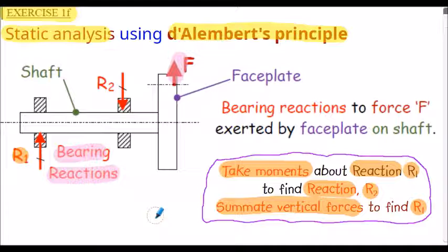So although this is a dynamic situation, the faceplate is actually rotating continuously, we can analyse it as a static situation using D'Alembert's principle and the centrifugal force acting on the faceplate. That is the force that will generate the reactions in the bearings, shown at R1 and R2. So again, a dynamic analysis using D'Alembert's principle is now being considered as a static analysis, and we apply static techniques we've used in previous lectures.